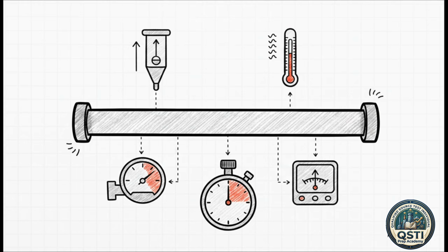And hey, when you're picking your metering device, you've got to make sure its capacity can handle both your expected maximum and minimum flow rates, factoring in things like molecular weight, dew point, corrosive characteristics, and your specific pipe size.